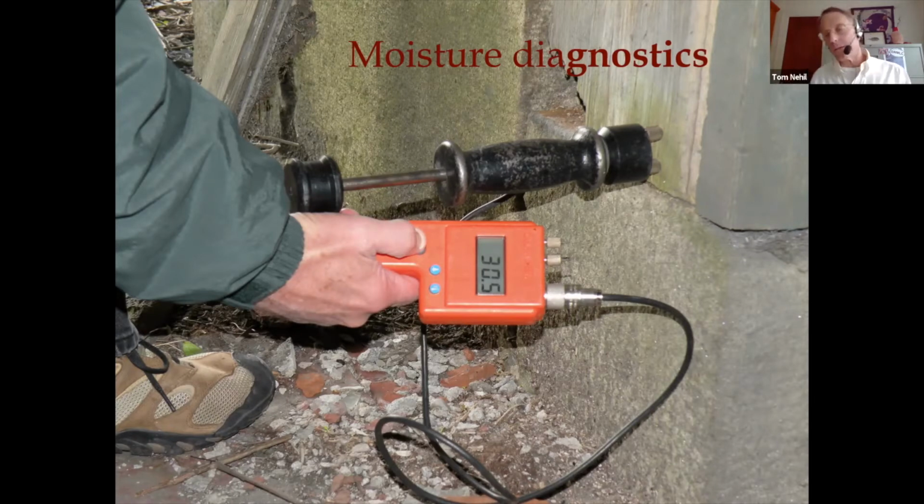And then we can look forward a little bit by using moisture diagnostics. And in so doing, what we want to determine is whether the wood is dry or not, because dry wood will not rot. Wet wood damage will continue to accumulate. So the magic number is basically 20%. If wood is drier than 20% moisture content, no further deterioration will occur.